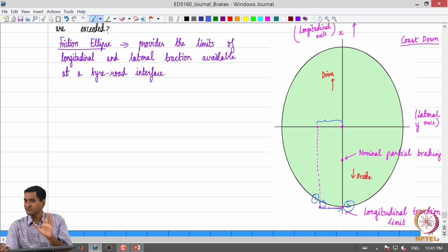We cannot change the area of the actuator in real time, it is fixed, at least in traditional brakes. So the only thing we can reduce is the brake pressure, and that is what the ABS does. It tries to detect this, figure out how much brake pressure reduction should happen, and reduces it, so that the brake pressure is lower than what is commanded by the driver.